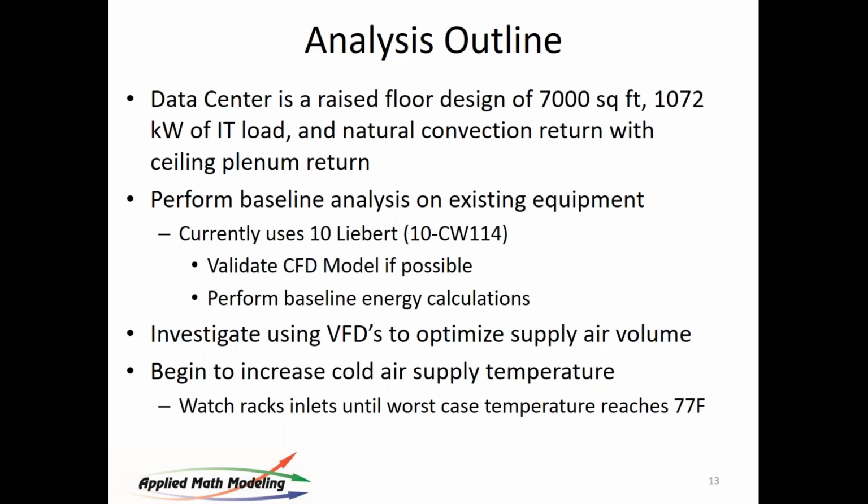There's 10 of them. We're going to first validate the CFD model if we can. Today we can't because it's a synthetic model. I made it. The point I'm making here is whenever you build a CFD model, you should validate it. You should, if it exists, because in the design phase, they don't exist. So you can do this if possible. Go in and make some measurements of what it is you've modeled to make sure your model is predicting the physical phenomena in the room. If it's not, then the model is not going to predict accurately any perturbations that you try to make to the model. The model should be as complicated as necessary and not more.